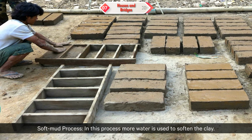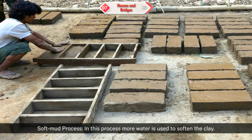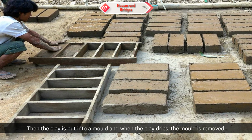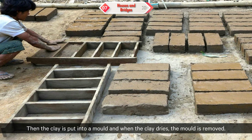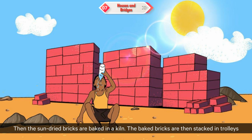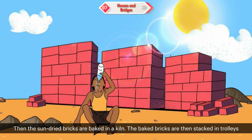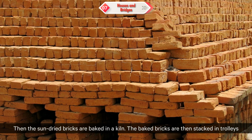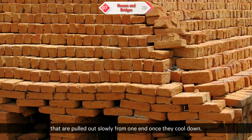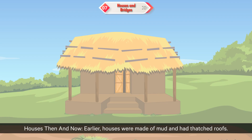Soft mud process: in this process, more water is used to soften the clay. Then the clay is put into a mold, and when the clay dries, the mold is removed. Then the sun-dried bricks are baked in a kiln. The baked bricks are then stacked in trolleys that are pulled out slowly from one end once they cool down.